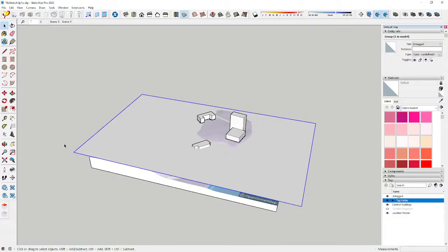I'm going to hit M and the Control key. Just touch the Control key. Now you see I have a little plus down there. What I'm doing now is moving this down, and I'm going to hold the arrow key to go straight down. There's a bunch of little things here that I may have said in the other video. I don't know. Some of them aren't that important. Others are. Anyway, I just moved that down. I'm going to type in 5 apostrophe for 5 feet. Now that's 5 feet below the one before it. And I'm going to now type in 30x.